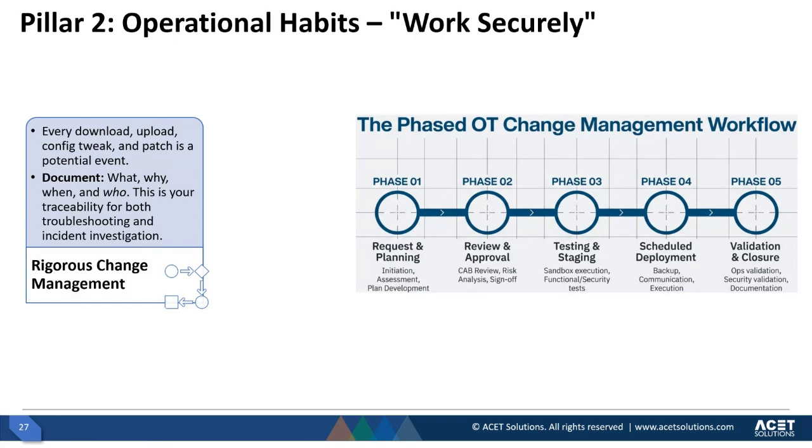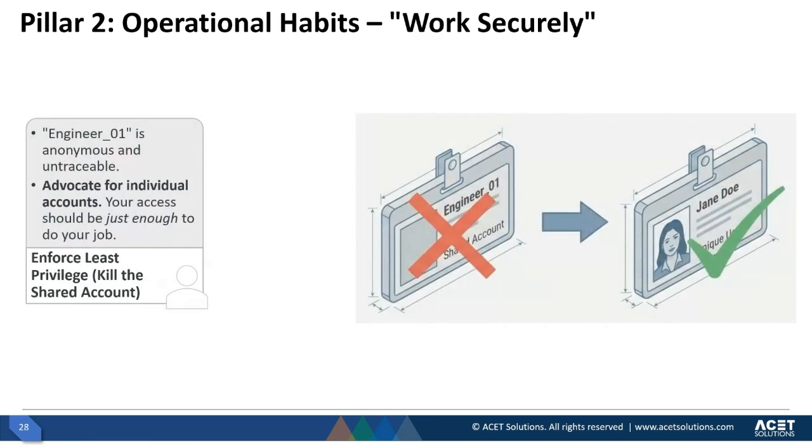And the second thing is shared accounts, like we used to do for engineer 01 or operator 1. We need to tell the vendors, and ask our IT team also, that individual user accounts are very important. Based on every person's account, we can properly rely on who is doing what, and enforce the least privilege so that only acceptable rights are given to the users.